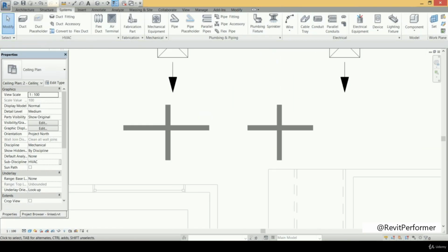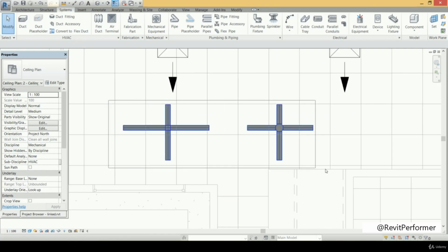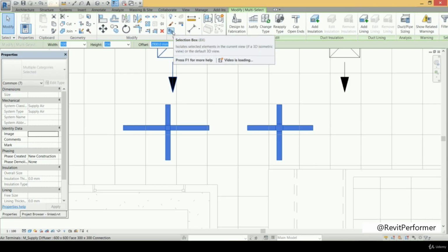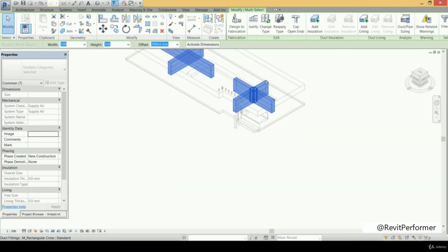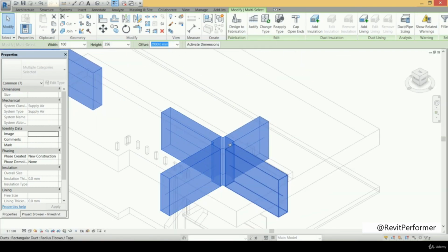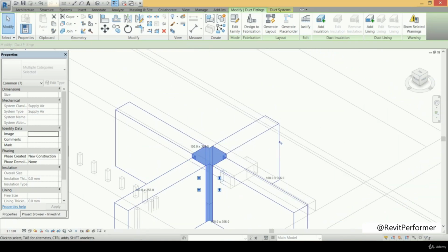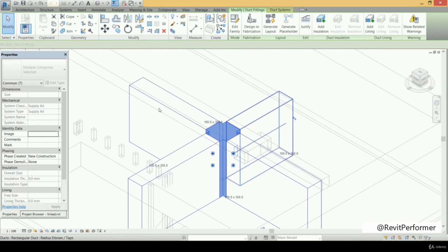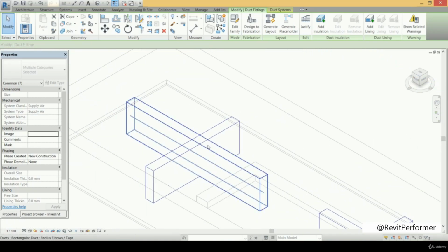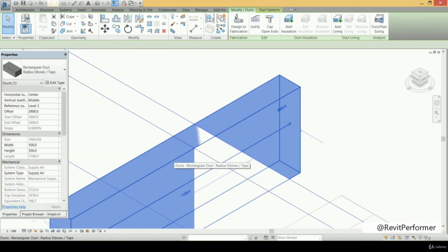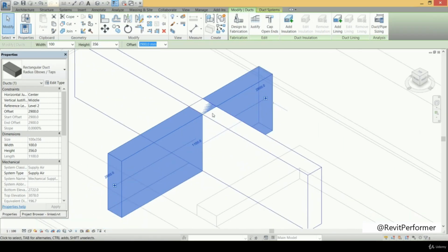And we can select them here and show them or express them in the 3D form. So if I go to that selection box, you can see those are the two types. This is a junction box, or it's a cross type that exactly connects the four ducts together. So this is a separate part from those four ducts. While on the other hand, for that type, we have two ducts that interfered with each other with no cross between each of them. Very good.